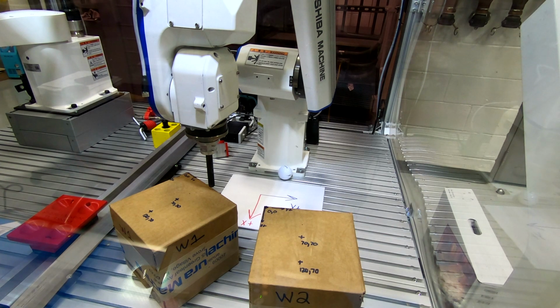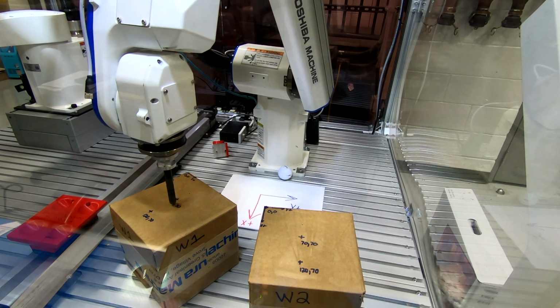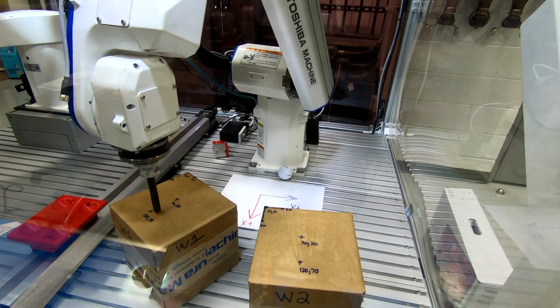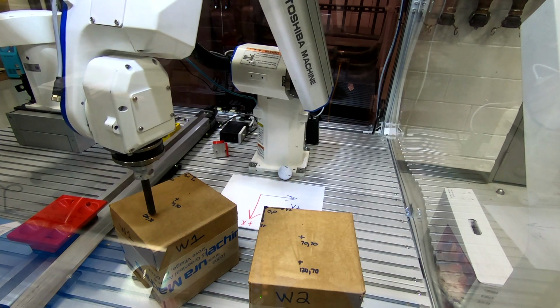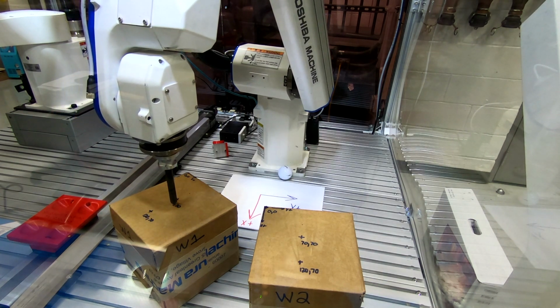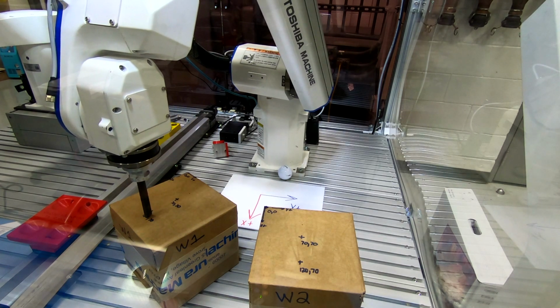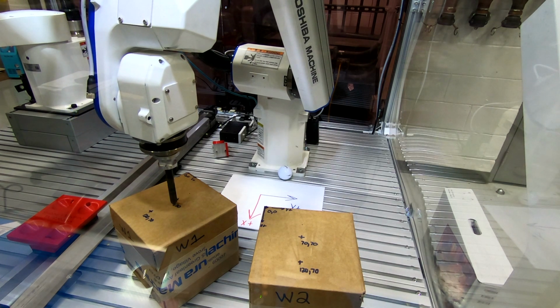So the servo is on, we're going to run our program. And you can see we're going to move to P1. And then we're going to move to P2. We're going to move back to P1 because we're going to loop our program and go to P2. Now where this becomes really clever is we can now change that work 1 coordinate space without having to reteach P1 and P2. So I'm just going to stop the program by letting go of the dead man switch.